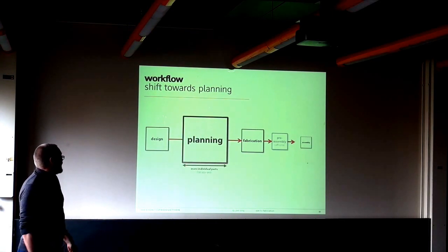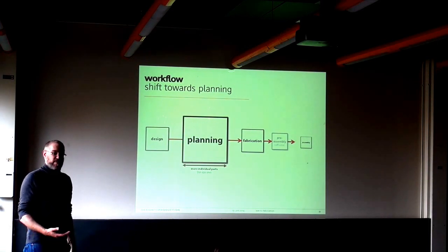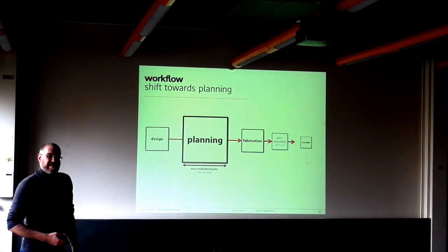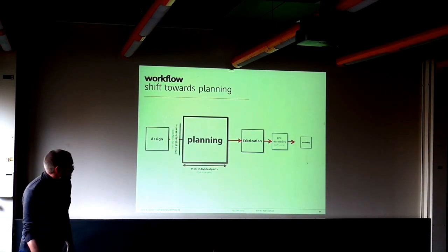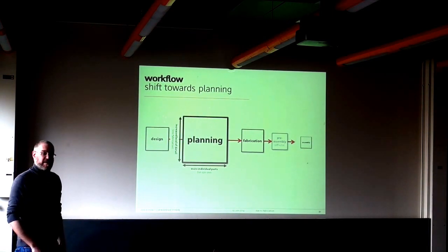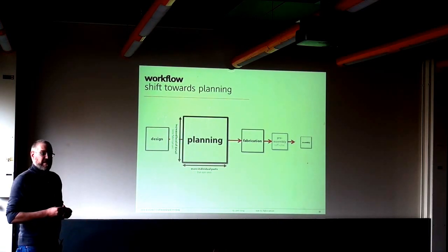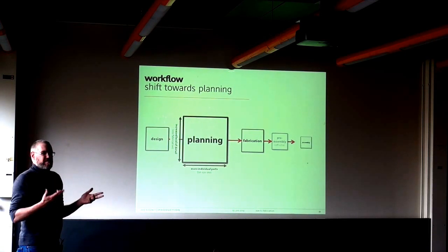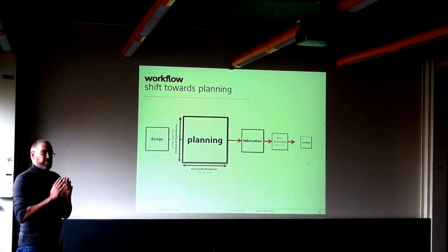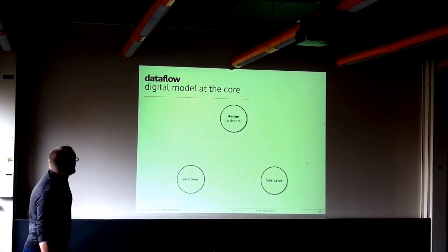And that comes from having more individual parts, which means someone has to basically draw workshop drawings for every single one of those 12,500 cladding boards that are in the facade. And on the other side, you have a much increased level of detail that you have to care about. Every single one of those 12,500 cladding boards has about 10 drilling holes and a few 5-axis cuts in there to fit precisely at the given place into the facade, that all have to be in the model.